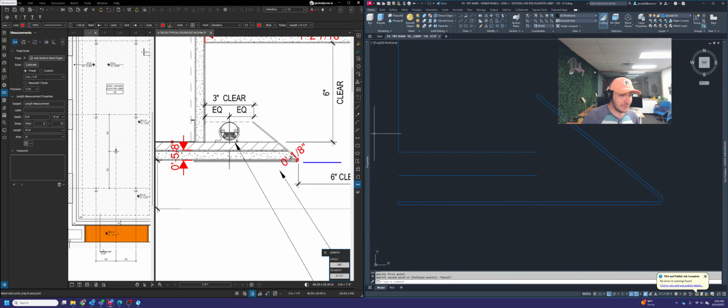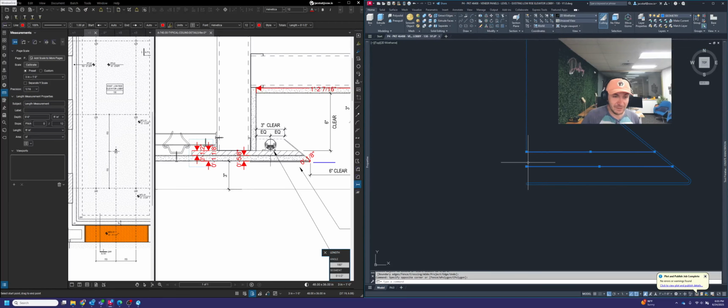These two lines are going to extend to the inside of our angle, so we're going to use the extend command to do that. And then they're going to extend past this a certain amount. It doesn't have to be perfect because I'm going to cut this off. I don't need to show the entire thing of what's happening over there, just enough to show the cove and the materials that are going into that cove. And I also need to draw a line here for the drywall as well. Okay, now that I got that, our cove is starting to look like what it's supposed to.